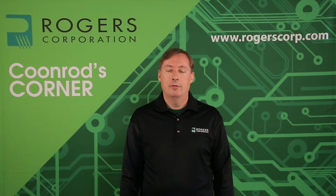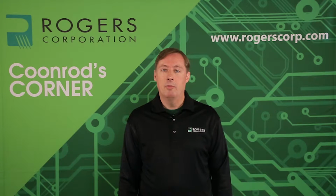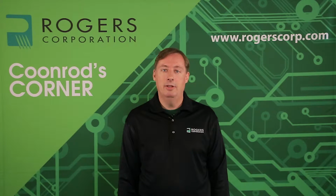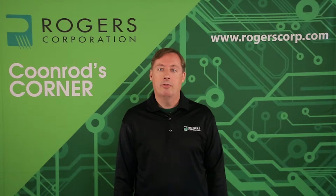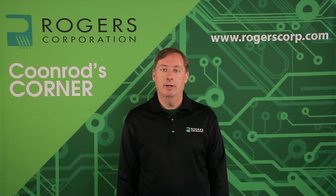There are two types of thermal management scenarios. Actually, it's a little more complicated than that, but just for keeping it simple today, we want to talk about just these two scenarios. One is device heating and the other is trace heating. Device heating is when an active device is placed onto a circuit and the circuit needs to deal with the thermal management of the device heating the circuit. Trace heating is when the trace of the circuit itself is being heated by applied RF power.